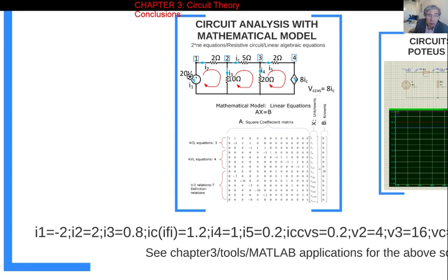This minus 40 watts means, since it is minus, that this equipment delivers power to our circuit. The amount of power delivered to this circuit is 40 watts. So in order to calculate this 40 watts, I need that I1.